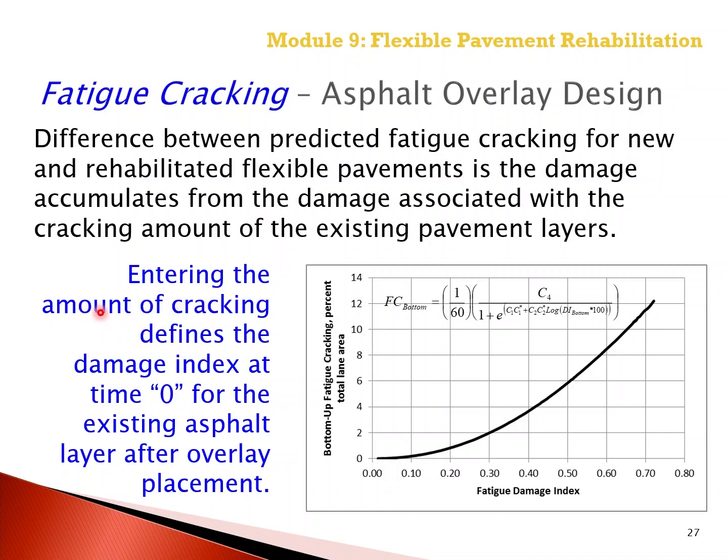So entering the amount of bottom-up fatigue cracking defines the damage index and the starting point at time 0 for the existing pavement layer after overlay placement.